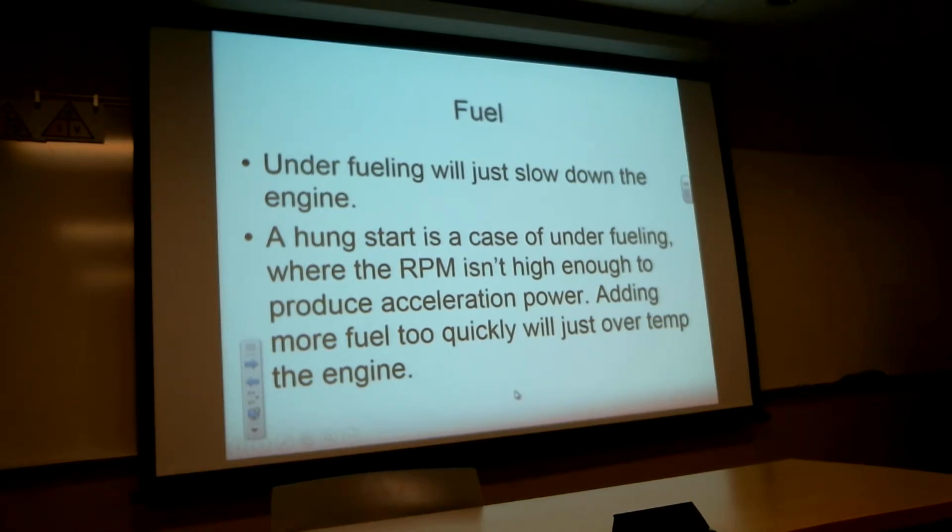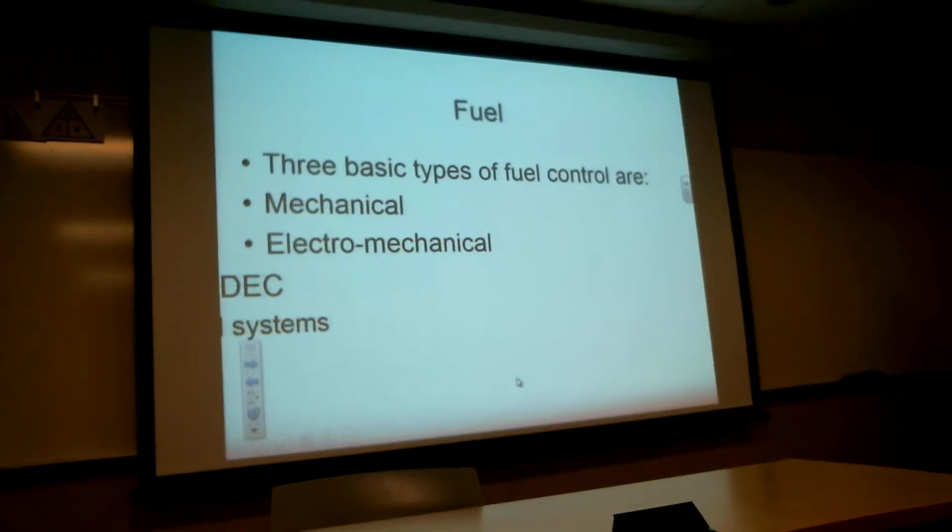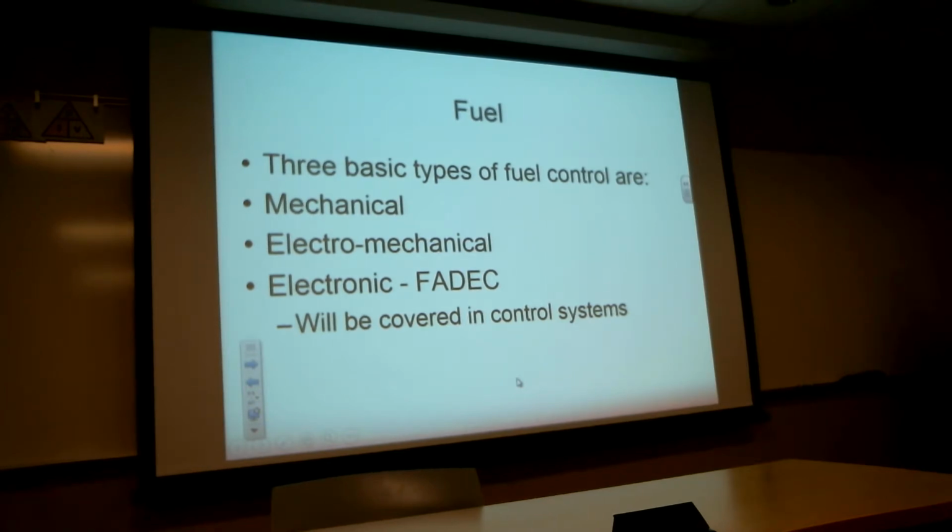Now this isn't so possible with FADEC controlled engines anymore. Most every modern engine is FADEC controlled, but there's still quite a lot of mechanically controlled fuel controls out there. They're like a carburetor. Some of you have seen your neighbors go out to work on their vehicles in the morning. A Harley is a good example. I've got a neighbor that has a Harley. You'd think a Harley would idle, but Harleys don't idle. They always have to go vroom, vroom, vroom, right? But only at 6 o'clock in the morning. That's a good case of mechanical fuel control, in which the owner is trying to warm the thing up. It'll warm up just as fast by driving it at some simple miles an hour, not gunning it. And the engine will probably live a lot longer, instead of dumping a lot of fuel into the cylinders, washing the oil off.